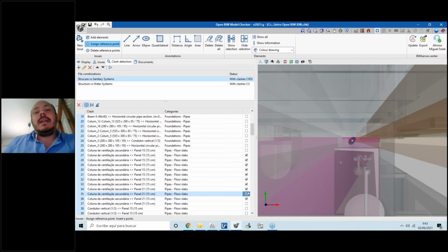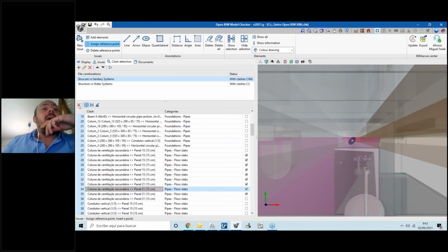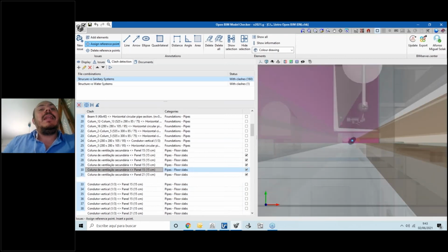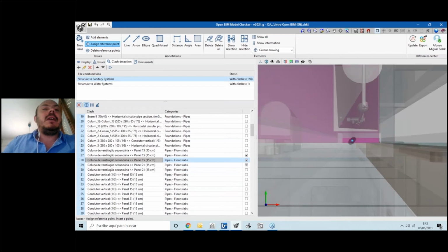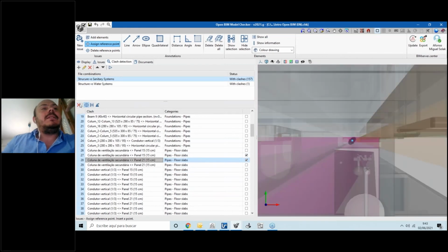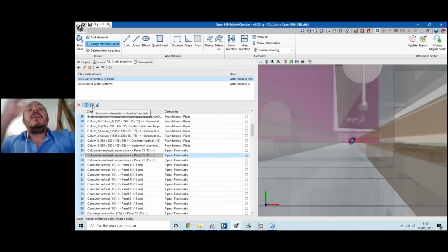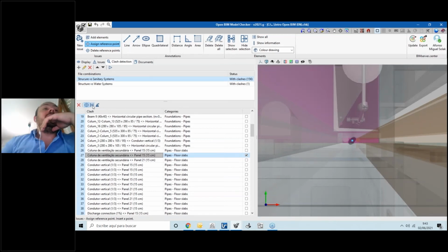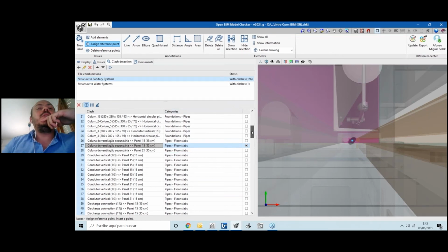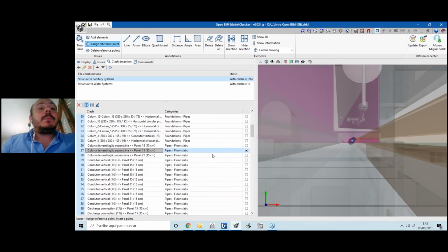So you can select these guys here and delete these clashes from our list of relevant clashes, let's say that. Okay, so we can delete the clash from our analysis. That could be useful, and sometimes we can have fewer issues and think a little bit more about the type of issues that we have, or how we are informing our colleagues about the problems, and not by just selecting all this information and sending to the team. Okay, so we can manage the clashes here.